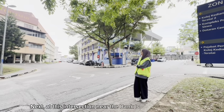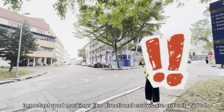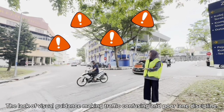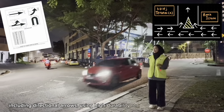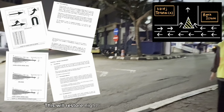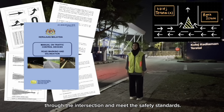Next, at this intersection near the bank, important road markings like directional arrows are critically faded. The lack of visual guidance makes traffic confusing and causes poor lane discipline. Our mitigation strategy is to repaint all junction road markings, including directional arrows, using high durability reflective thermoplastic road paint. This will restore nighttime visibility, guide drivers safely through the intersection, and meet the safety standard.